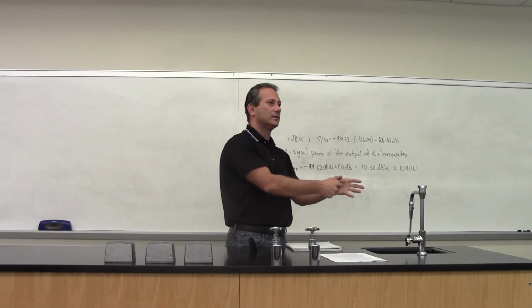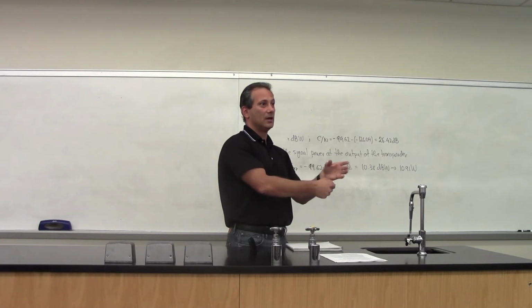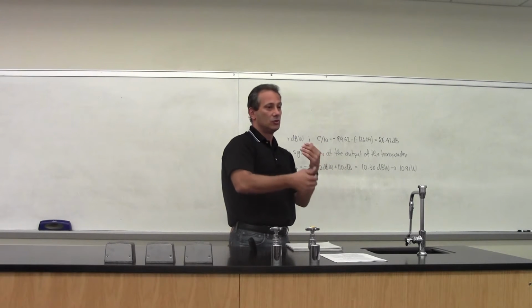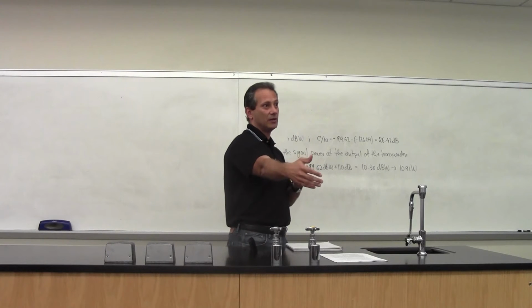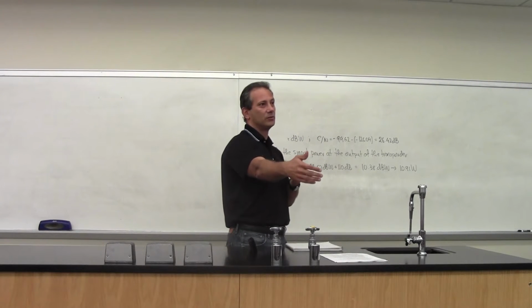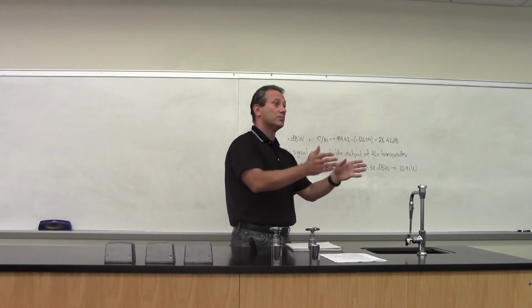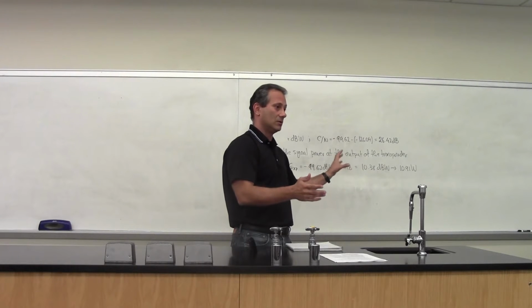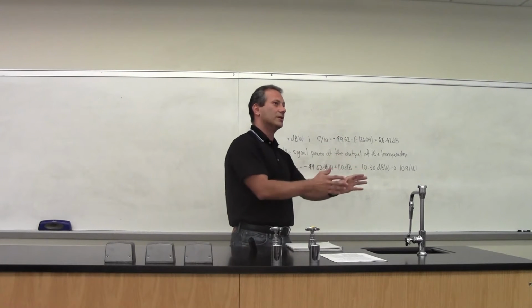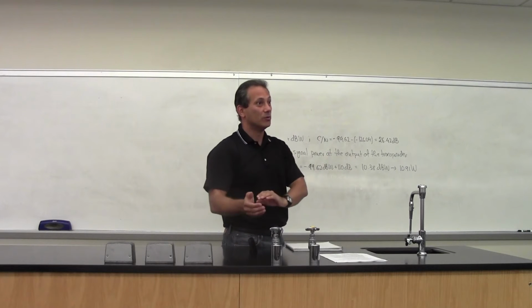So that's why that system temperature is 500 K and not 270. Out of that 500 K, 270 is because you're staring at the hot earth, which has a temperature of 270. The other one is the noise temperature from internal components of the transponder. The transponder in this model is noise free, but all the noise is moved to the input.